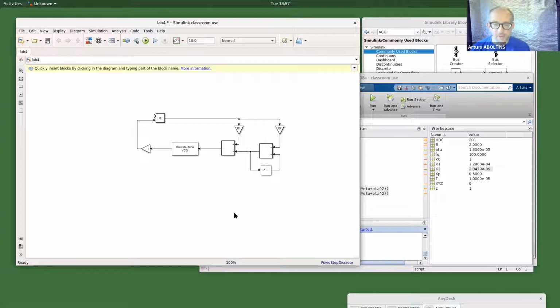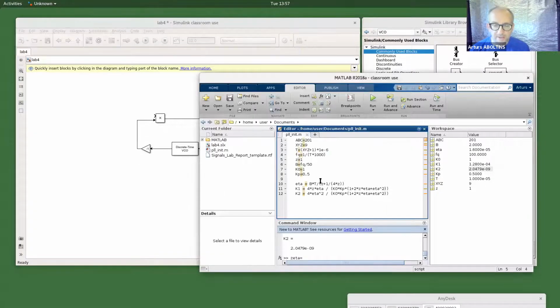And also, when you design, you should refer to those variables. The first time, MATLAB will complain that those variables are unknown, because they get initialized when you run the model. This is kind of an inconvenience compared to the separate script.